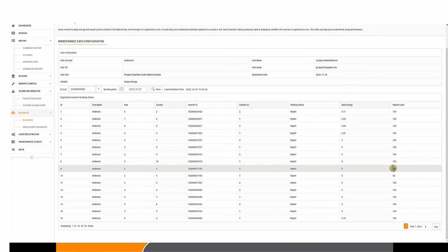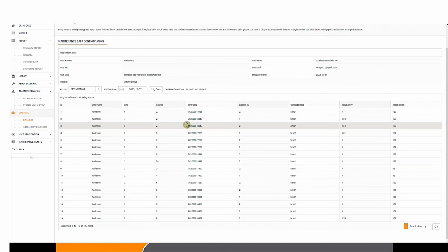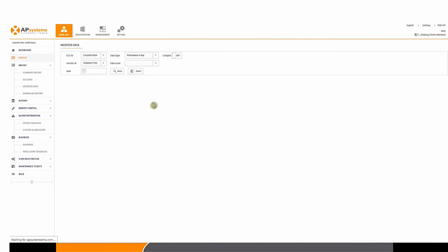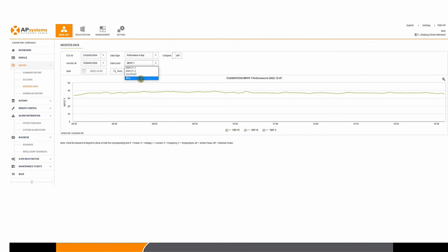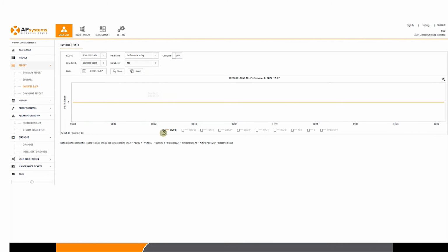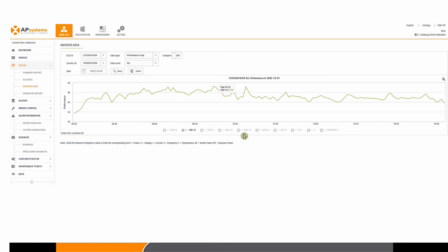So clearly it's nothing to do with the inverter, and also you can tell it's nothing to do with the panels as well, because if I look at the VOC of both channels, the panels are producing power. It's normal. So like you see, if something were wrong with the panels, that would show like 10, 20, depending how many diodes they have. So it might show 10 volts. So that's a good tool. Okay.